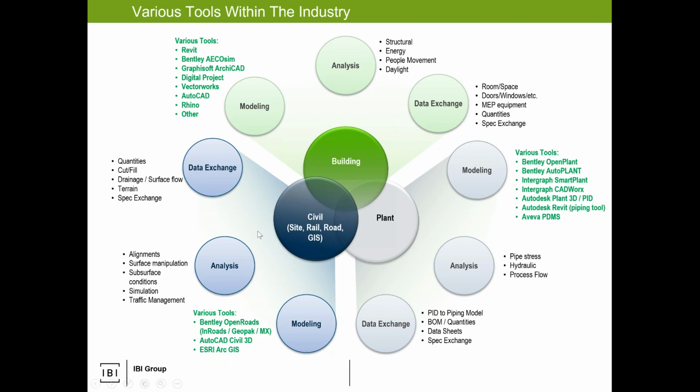Now, the problem comes when you're on the civil side and somebody says, well, I need to model the terrain. Well, Revit has the terrain button, I'll just do it in Revit. Keep in mind that's a building tool. So when we get into civil engineering, true cut-fill analysis, delineation of subsurface gradation, buried utilities, buried pipe networks, gravity versus pressure, then we start getting into the valves and the continuity of flow streams and everything.